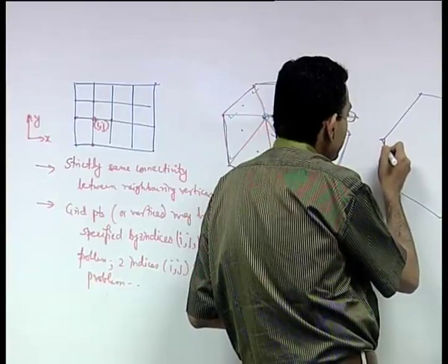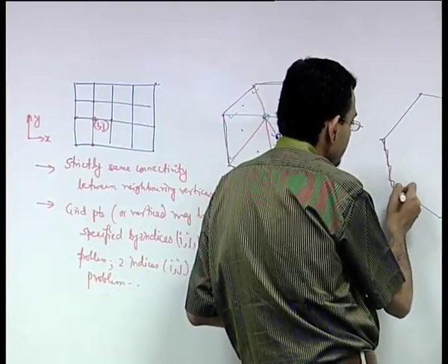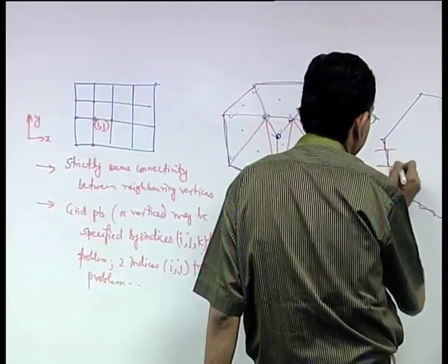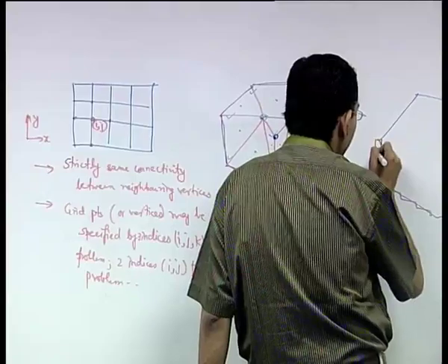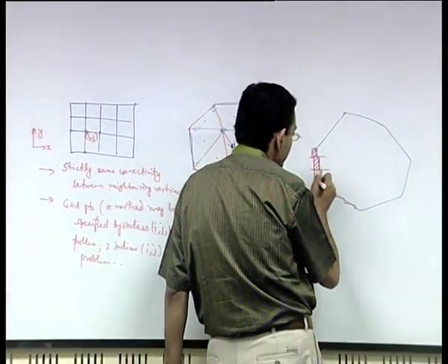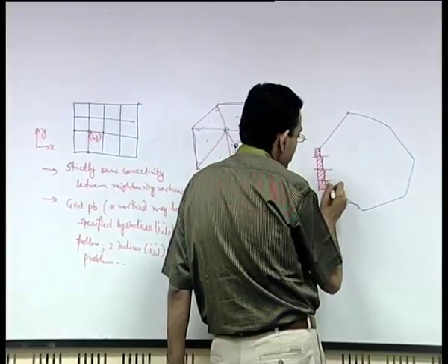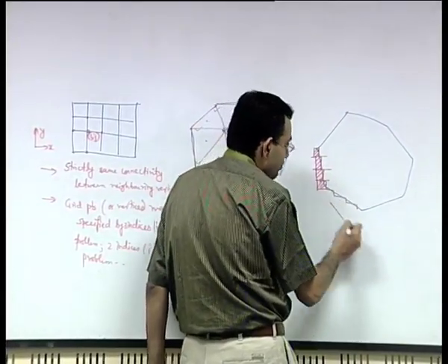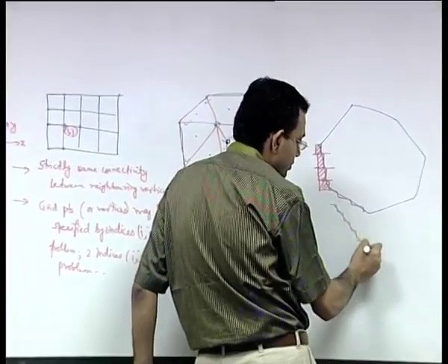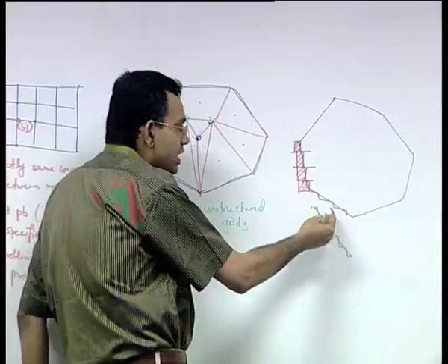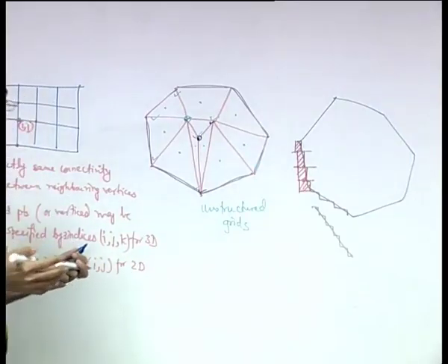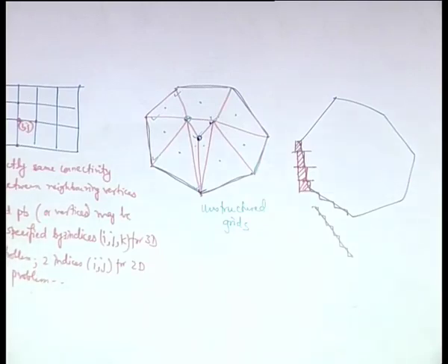People used to represent these in steps like this, where there will be certain control volumes which are blocked off, so that whatever is a line like this is represented by steps, and whatever part is blocked off, artificially some other properties are given, for example very high viscosity, so that there is no flow. So, this type of representation is given.